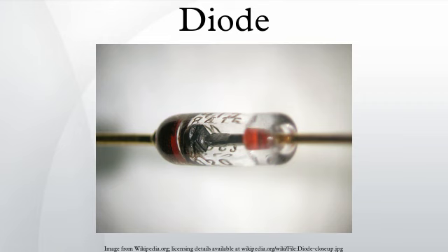However, diodes can have more complicated behavior than this simple on-off action, due to their nonlinear current-voltage characteristics. Semiconductor diodes begin conducting electricity only if a certain threshold voltage or cut-in voltage is present in the forward direction. The voltage drop across a forward-biased diode varies only a little with the current, and is a function of temperature. This effect can be used as a temperature sensor or voltage reference.